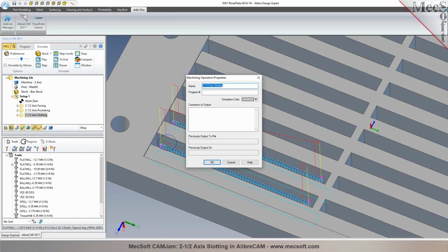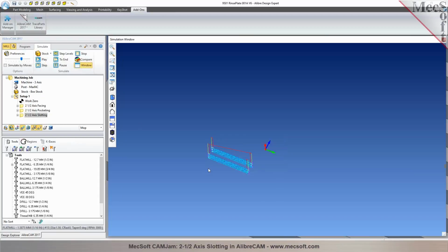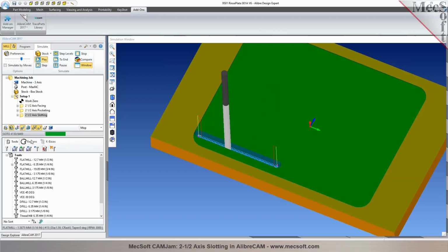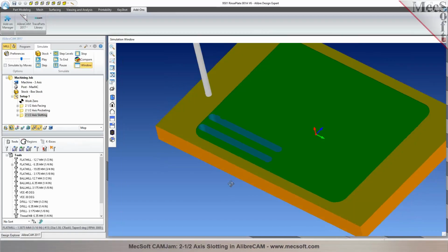Okay. So what's the downside of setting that to a very high accuracy? Well, it depends on what your machine can handle, right? If your machine is not capable of handling a tighter tolerance, or number of decimal accuracy, then the machine may not have enough look ahead, so you might see some kind of a jerky motion on the machine since it's not able to find that many close points.